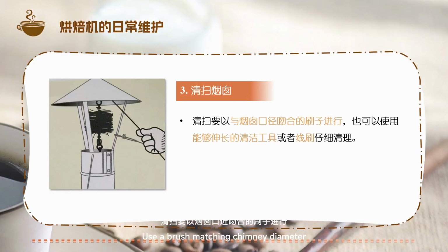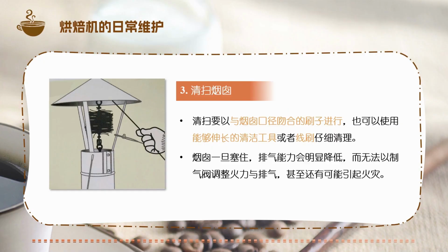Use a brush matching chimney diameter. Alternatively, use extendable cleaning tools or wire brushes for thorough cleaning. Chimney blockage significantly reduces exhaust capacity, preventing airflow adjustment via damper, and may even cause fires.